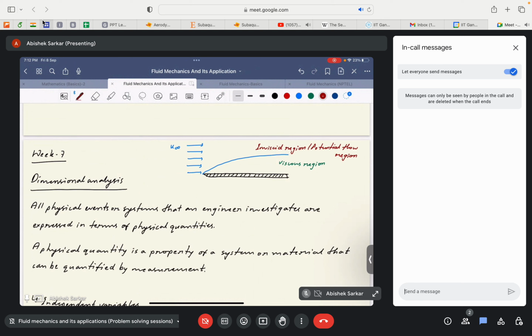The concept of boundary layer, developed by Ludwig Prandtl, essentially tells us that the majority of the flow over a flat plate or any surface can be studied by potential flow theory, and ideally assumed to be inviscid, since Euler's equation or the potential flow equations will be good enough to predict the motion of fluid in those inviscid or potential flow regions.